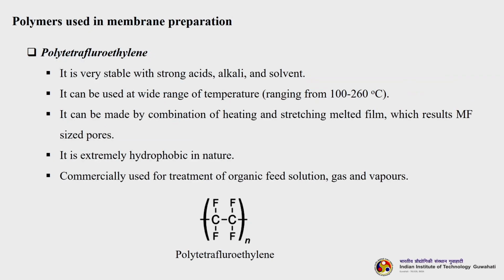The next class is PTFE, which is called polytetrafluoroethylene. It is also very stable with strong acids, alkalis and solvents. It can be used at a wide range of temperatures, usually it can withstand up to 260 degrees centigrade. It can be made by a combination of heating and stretching melted film, which results in microfiltration-sized pores. It is easy to fabricate also.